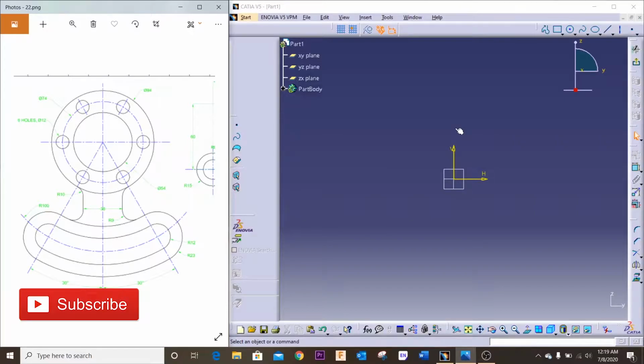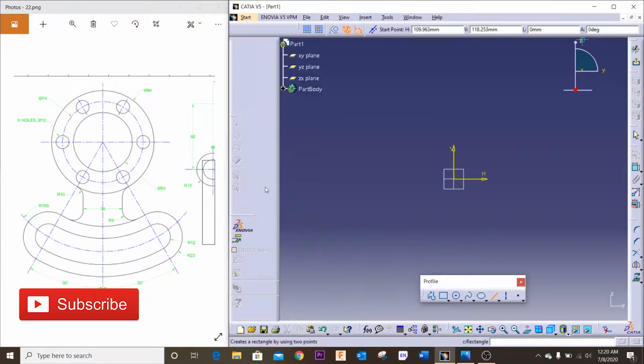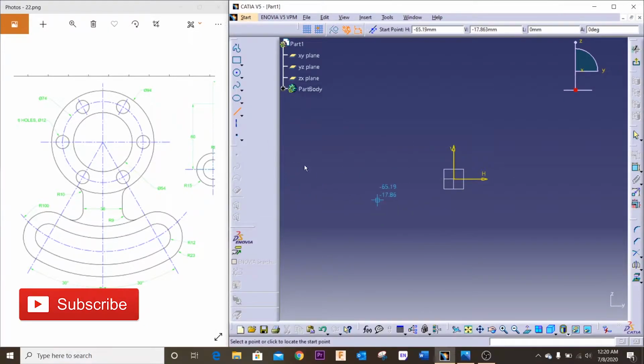The first step in this video is we're going to make a construction line, this one, so that this is a vertical axis here, or vertical construction line, whatever you want. So I'm going to select the line, which I've already selected. I'll bring this down here. Yeah, so there's the line. I'm gonna select this construction / standard element so that it makes it a construction line, and I'm gonna make it go straight through the vertical axis here.